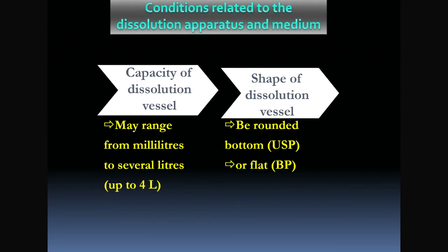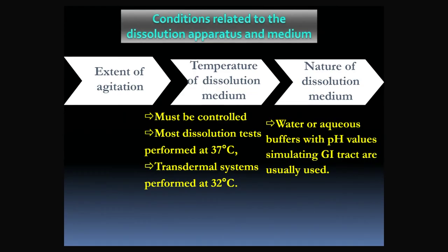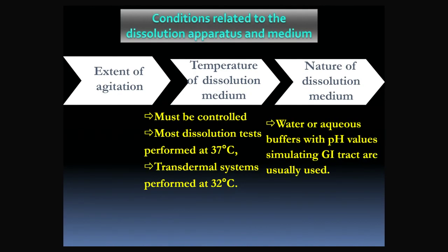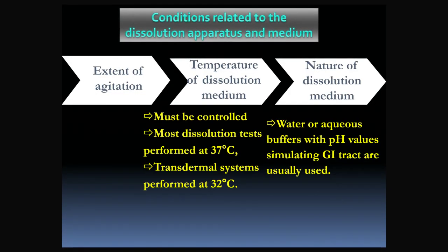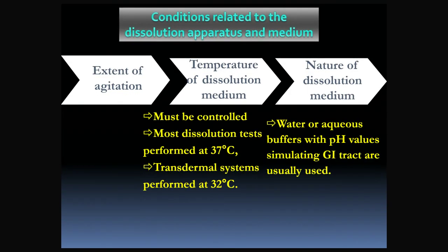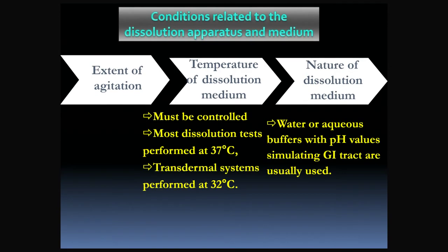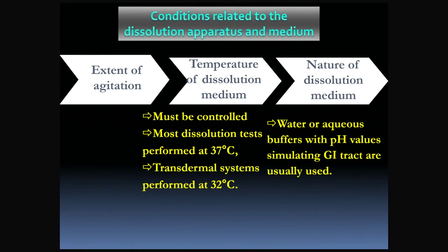by a disintegrating tablet? The extent of agitation serves as a mechanical control that dictates the thickness of the stagnant boundary layer, where increasing the rotational speed effectively raises the mass transfer coefficient to accelerate molecular diffusion.